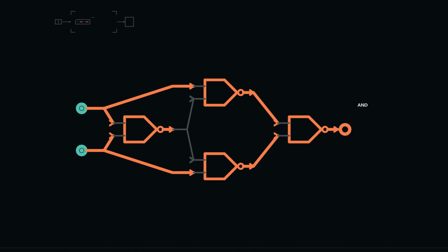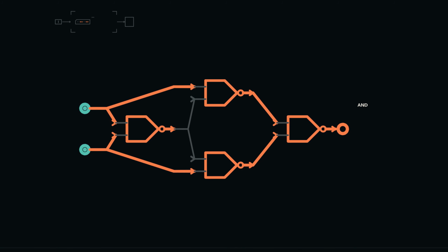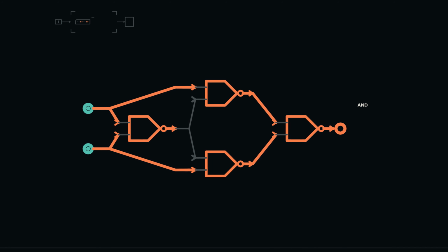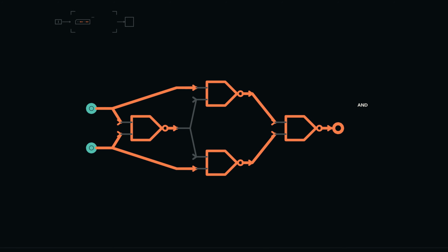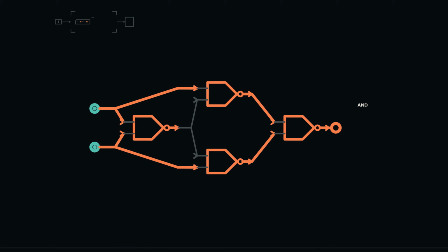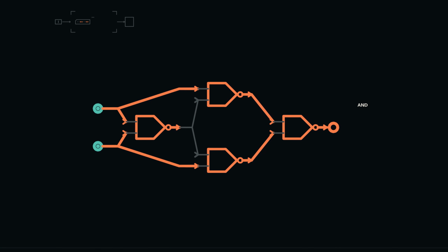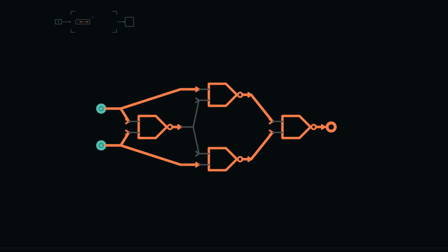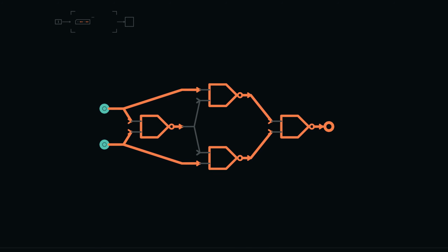For matching row 1, 1, N1 becomes 0. Then both N2 and N3 see 1 and 0, so both become 1. Again, the final NAND receives 1, 1 and produces 0. Matching inputs have reached the required 0 by 2 different internal traces.